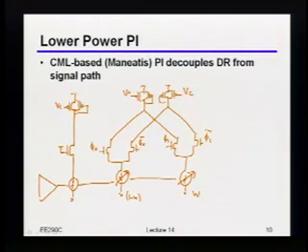So what I'm going to do is take an op amp and control that voltage over there so that that swing is set by the VC. In other words, I know that when this is pulled down, the input is high, or VDD. So all I'm doing is using this op amp to ensure that when that input is indeed high, I get that control voltage of swing. Does this make sense to people?